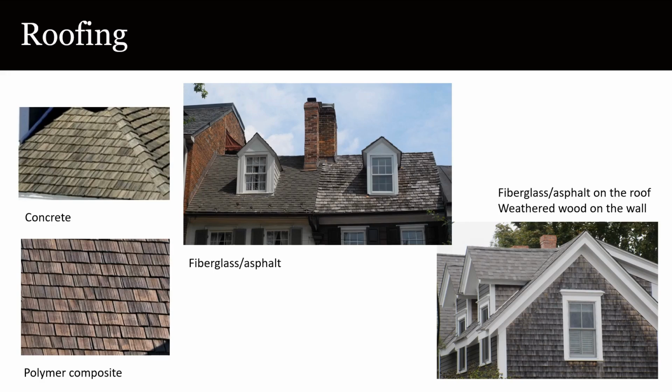Just as fiberglass-based asphalt roofing is not similar enough to slate to generally be considered a substitute for it, neither are those fiberglass shingles that attempt to evoke wood shingles generally considered a good substitute for replacing an existing historic wood roof. But when the color is carefully selected, some products in this class may approximate the scale and texture of a wood roof adequately enough to be a choice for replacing a roof that was historically wood but has long been lost to asphalt shingles.